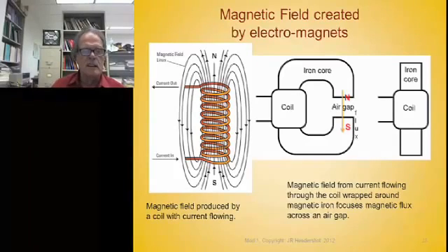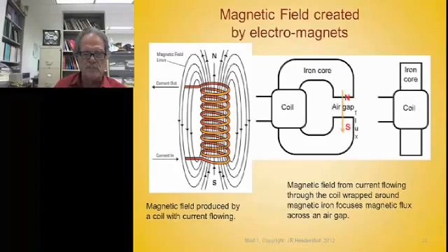Let's take this conductor and wrap a bunch of turns into a coil like this. You could wrap this around a broomstick handle and pull the broomstick out of the coil of wire. If you put a voltage across there, you get a current to flow inside that wire, and you get flux, a magnetic field that rotates toroidally like a donut around each one of those conductors.